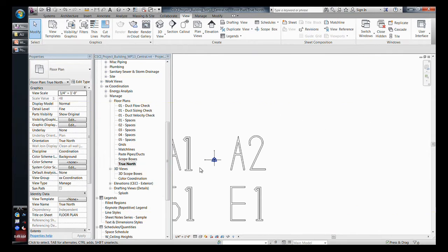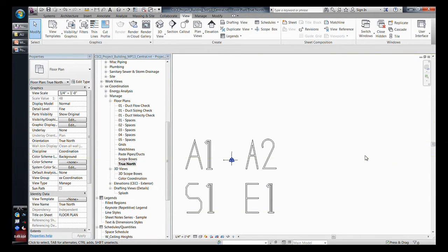And whenever I get a project and the project is way out here, I get a very quick sense of how far off they are from the 0, 0. We know that Revit doesn't like this very well with really extreme large numbers. So for me, I see value to know how the architect is managing coordinates and how familiar they are with this type of stuff. Again, this is the view that is set to true north, where all of my other views are set to project north.